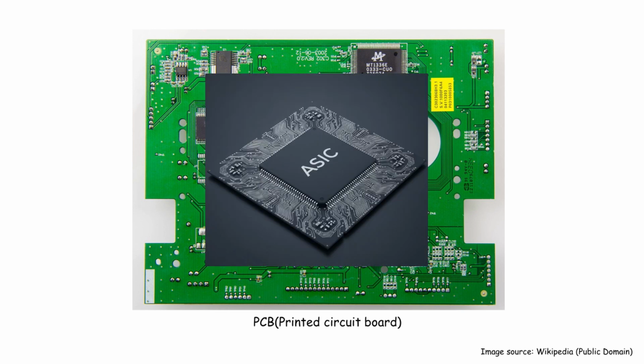Just like a breadboard allows you to change wire connections on the spot, an FPGA lets you modify your design immediately. If there's a mistake on a breadboard, you can simply move a wire. With an FPGA, you only need to change the HDL code and rerun placement and routing. This flexibility is one of the FPGA's greatest strengths.